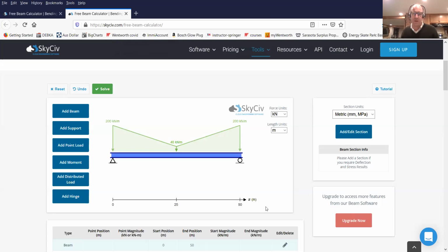Well, I think everybody knows that the mass of a car is about 2,000 pounds, right? Maybe we should double that and use a safety factor of 2 and say that they're 4,000 pounds, because there could be trucks, there could be cars. Trucks are heavier than cars. So we go with an average of 4,000 pounds.